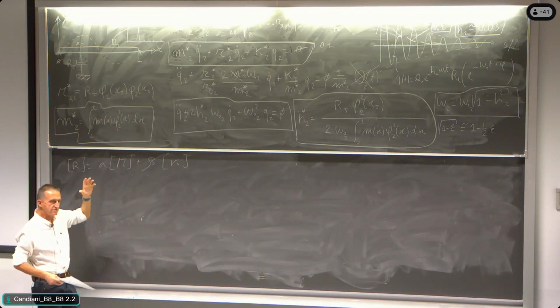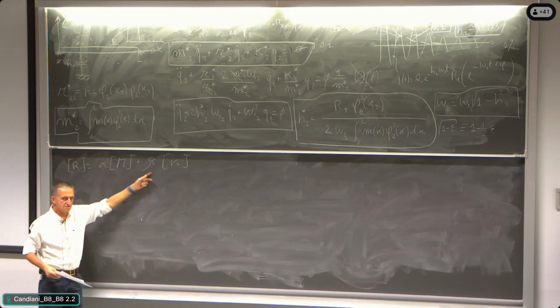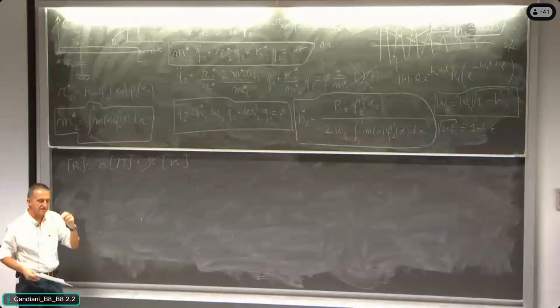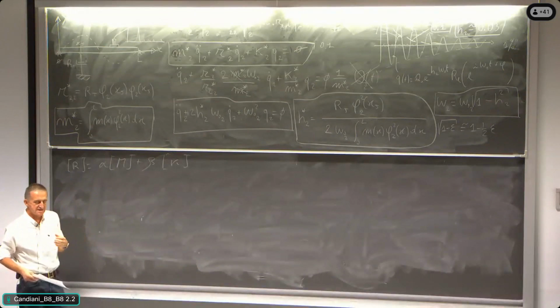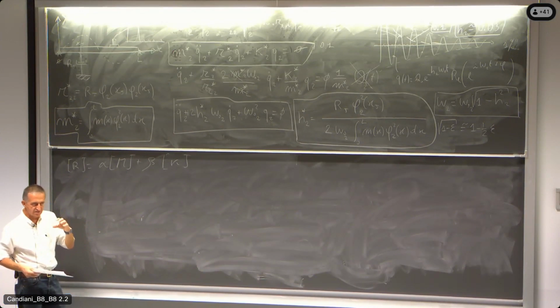So we are proposing a damping matrix that is given like that. All of that could appear something that is a bit rude. So we have two real numbers that are taking care of the distribution of damping. So it will be a representation that is a bit far away from all the possibilities that can happen in a real system. All right, but the point is that we are speaking about distributed damping, something that is associated not to some concentrated elements, but to a general distribution of damping in the system.